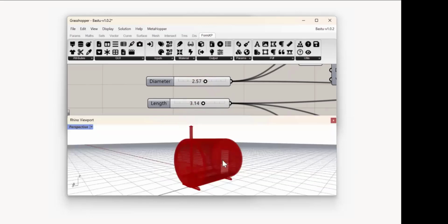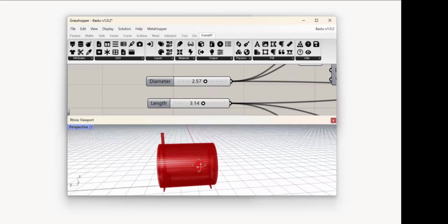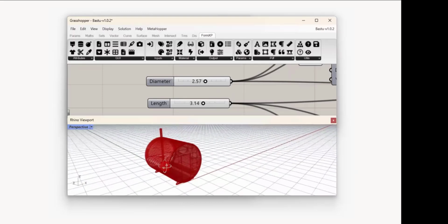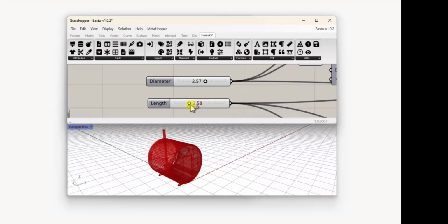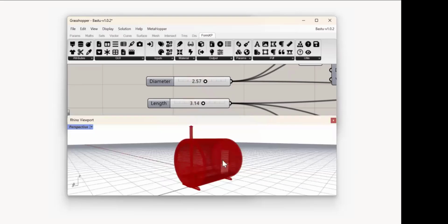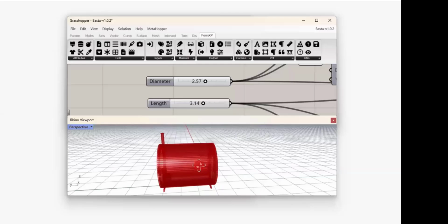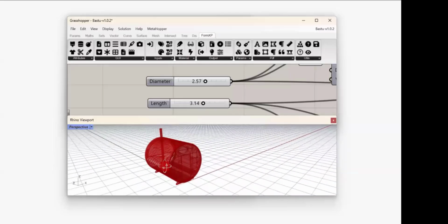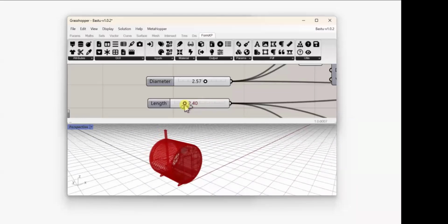And always work with meshes. That's the other thing. Be in control of how big these meshes are and how they're put together. The file size of the 3D model is extremely important, because it's created on the server, and then that needs to be sent to the client. And you know what happens if you try to download a big file? It can take forever. So always make sure that you have really, really tight and small 3D models.